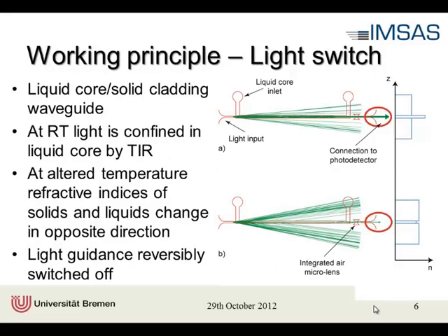To show that this principle is working, we build up a liquid core solid cladding waveguide on a chip. That means that we use a microfluidic channel, here illustrated by those red lines, which we filled with our core medium, a liquid. And the surrounding chip material, so all this white part here actually, is the cladding of this waveguide.